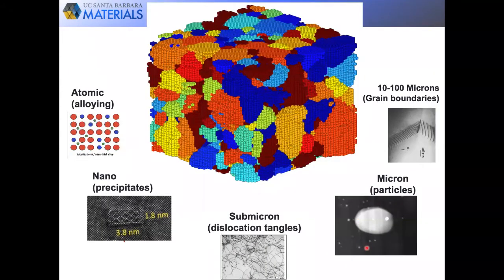So metals have many outstanding qualities. One of their downfalls, however, is that they are dense, they are heavy. So there's been an age-old, long-standing initiative to make them stronger, and so less metal can be used. So it's no surprise that we do not use pure metals. Instead, we invoke numerous ways to strengthen metals. Most of these methods make it more difficult for dislocations to move. That's usually the key idea.